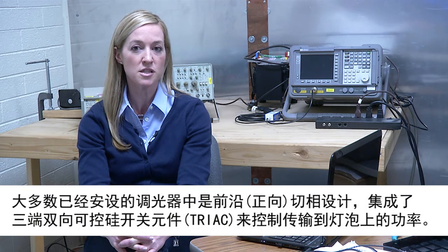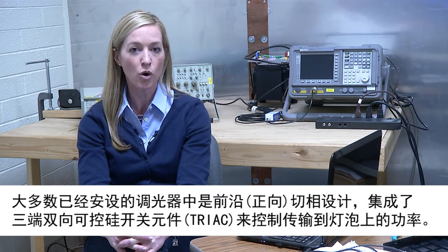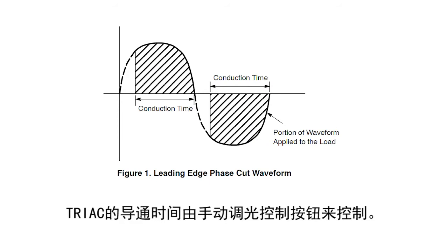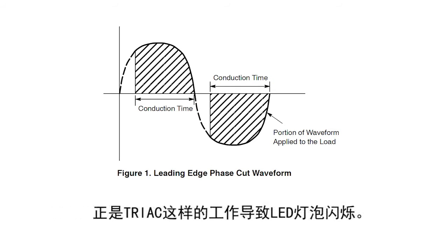The majority of installed dimmers are of the leading edge, forward phase cut design and incorporate a triac to control the amount of power passed onto the bulb. The turn-on time on the triac is controlled by the manual dimming control button. The triac will then remain on until the AC signal crosses through zero, then it will turn off. It is this characteristic of the triac that causes the flickering of the LED bulbs.